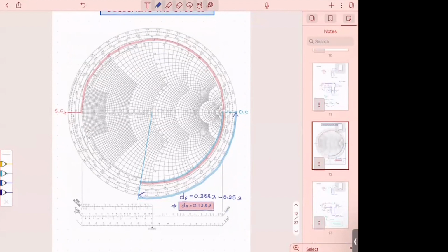And this is an open circuit and this is a short circuit. All right. You need to remember that. Since I'm going to always move, the short circuit for the stub is the load. Remember that? So as I move up to its input port, I move towards the generator. I'm at the end of the short stub, and anyway, I have to go towards the generator. Right?